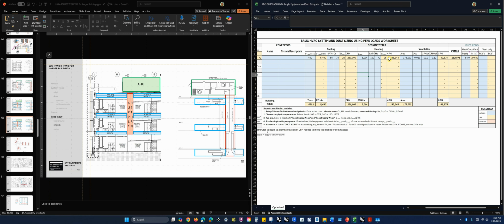We have to find a boiler, if that's what we're using, that has a peak output of 5,000 kilo-BTUs. By the way, if you want to get technical about this, remember a boiler is not 100% efficient. So if we need to deliver 5,000 kilo-BTUs, we really need to have like 5,000 times 1.2 probably if it's an 80% efficient boiler. So it needs to be bigger than that a little bit.